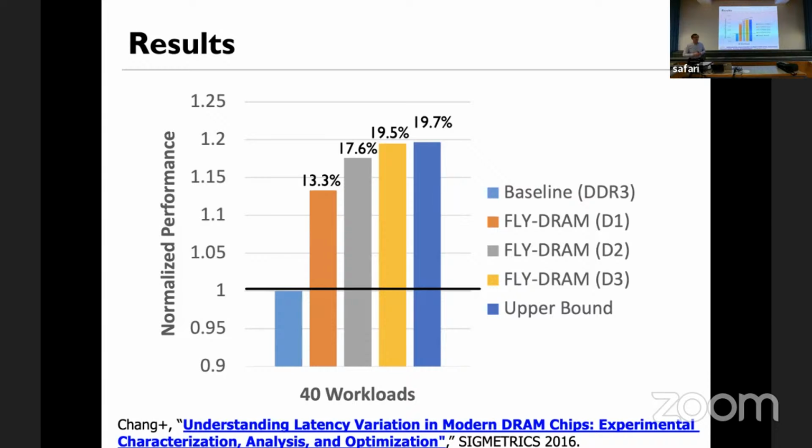So you can approximate the performance of the upper bound, but now your performance depends on what kind of module is in your system. So there's some performance variability that you introduce. This performance variability already exists because of the way process variations show up in CPUs, but this amplifies it. For example, all of us who have the same phone, all of those phones are accessing memory at the same latency. But now, if I'm lucky, I'll get 20% additional improvement. If you're unlucky, you'll get 13% additional improvement. And maybe if you're really unlucky, you'll get somewhere around here, right? So there's some performance variability. I don't believe that's a huge deal because there's a lot of performance variability that already exists.